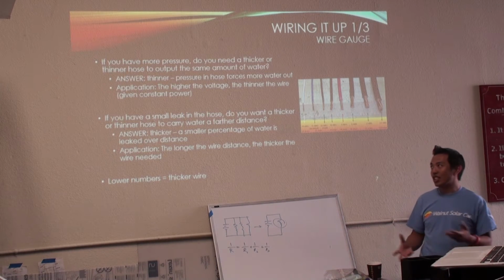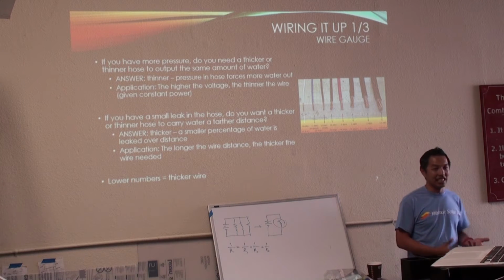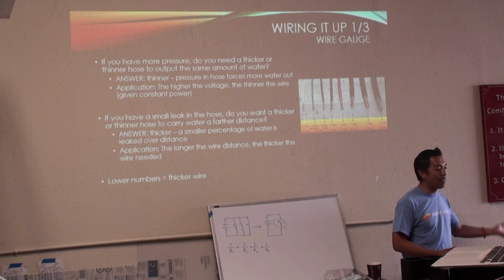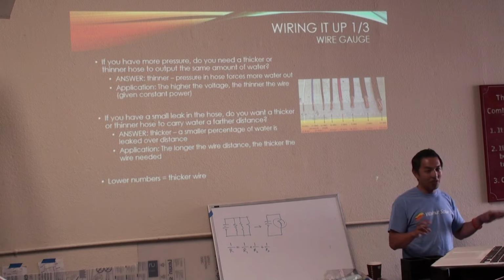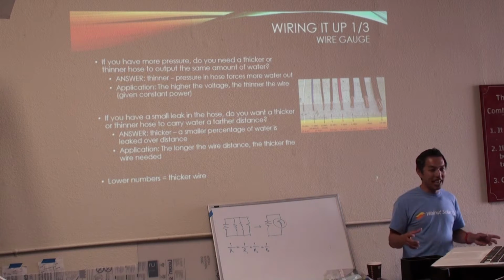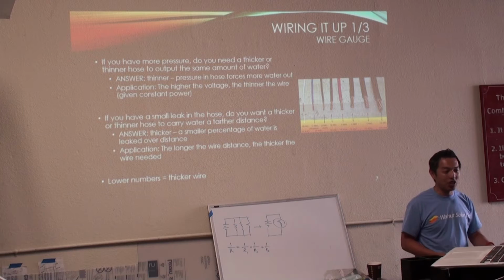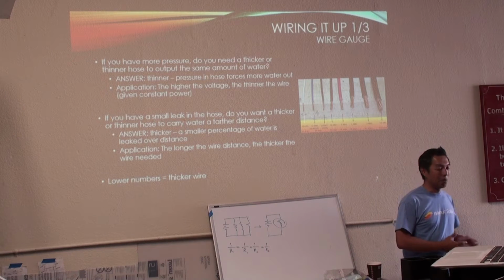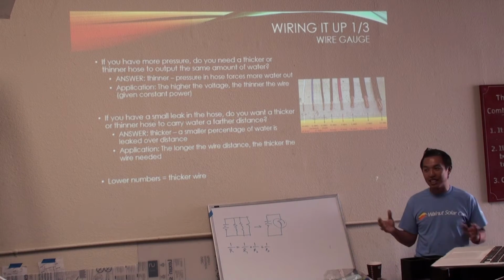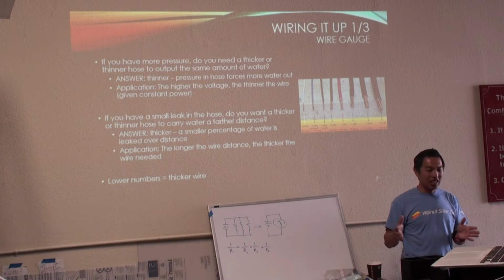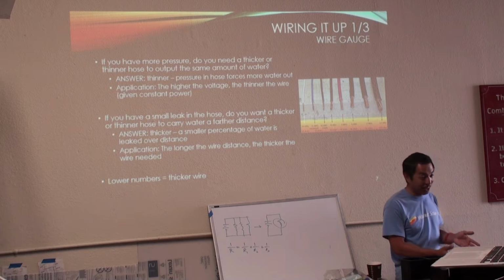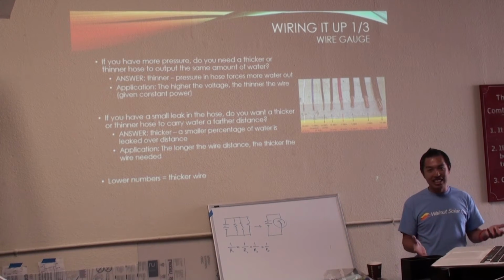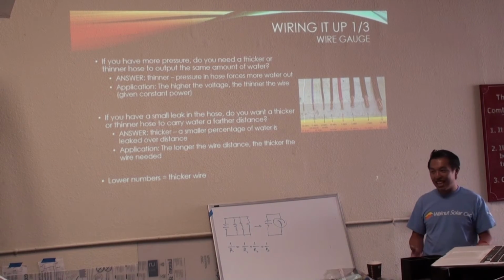So this is the debate that people have had in solar car racing: do I want to run at, let's say, a 48 volt system that would be safer because you don't have a high voltage, but then it means that you need higher current, which also means that you need thicker wires, as compared to people who run at 72, 84, 96 volts. They can run at about half the current, which means that their wires can be thinner. It's a safety versus weight thing.